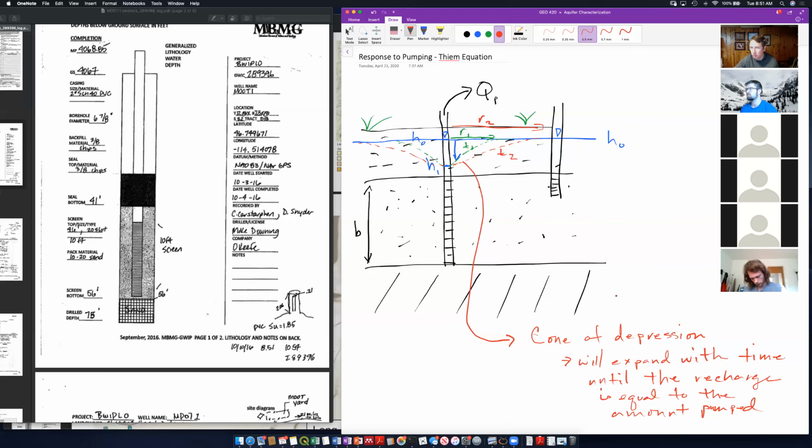So generally H1 will drop to a pretty constant value. But when we do a test, we'll often regulate to make sure the discharge is constant, in which case H1 will get to a constant spot because the pump's efficiency will basically dictate what the height is in order to get this discharge. We're going to say for now that H1 remains the same.